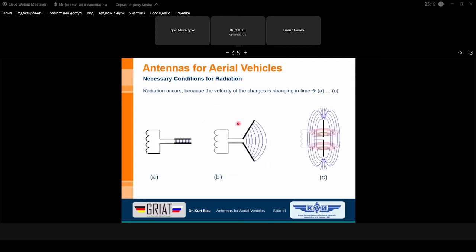This was an example of how we can imagine a single resonance circuit coming only from a charged capacitor. The capacitor is charged but not connected to the coil, not connected to this inductance. Otherwise, it's not possible to charge it, because this is a short circuit for the capacitor. First the capacitor is charged, then it's connected. In the moment it's connected, we have oscillation with decreasing magnitude.